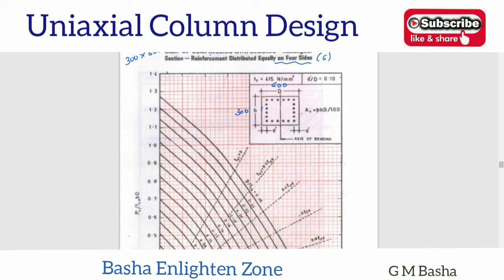So here itself I will take that down. What is the d dash value? I told you d dash is the effective cover. According to the chart, the minimum clear cover we have to maintain for a particular column will be equal to 40. So 40 clear cover minimum for columns.